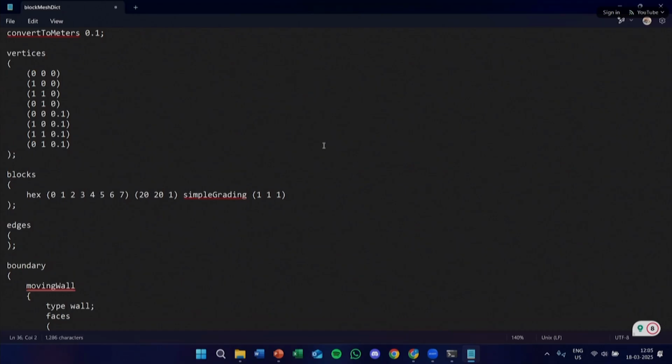If the geometry is very complex, how do we make the geometry here? In case you have a very complex geometry, you can always create the CAD file within any software, even ANSYS, and then use snappyHexMesh to make a mesh for that. For snappyHexMesh, we also held a workshop last year in November. It's on YouTube also, so you can check how to go about using snappyHexMesh. Okay, thank you.